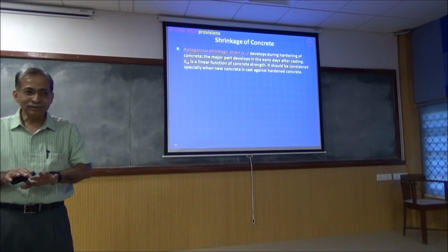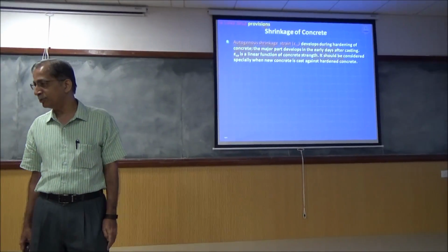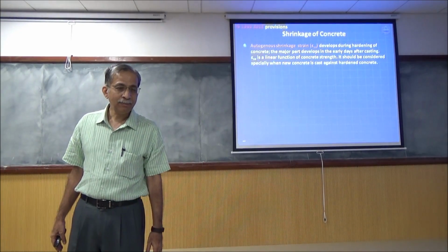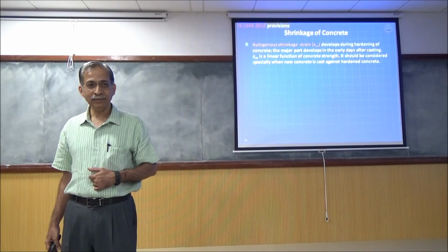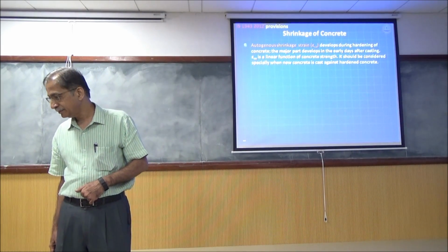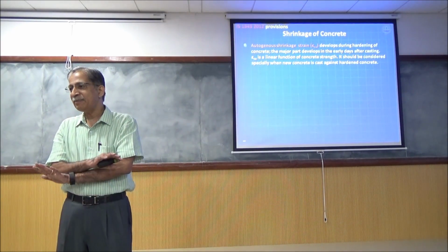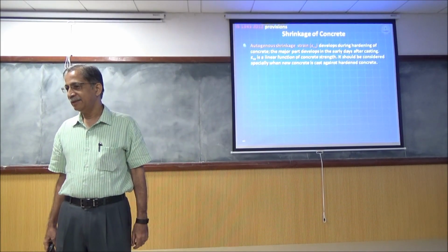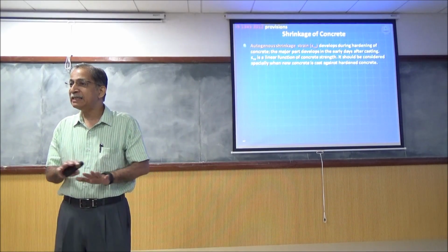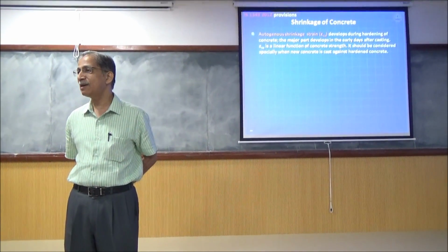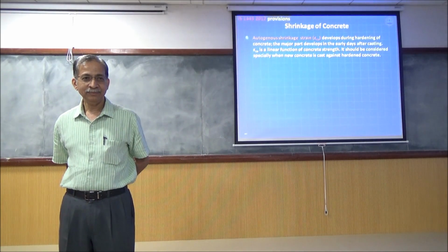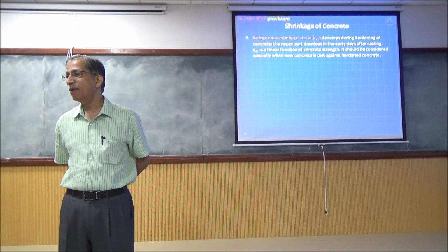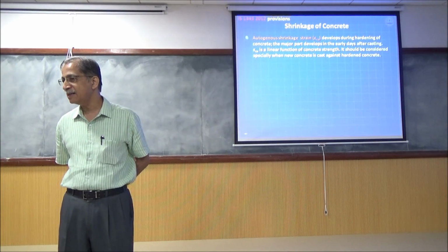If you want to minimize this shrinkage, what should you do? Simple solution. Provide water. How will you provide water? Curing. Keep the surface wet. Continuously wet or continually wet? What's the difference between continuous and continual? Very important words in English, no? Those words are very precise.